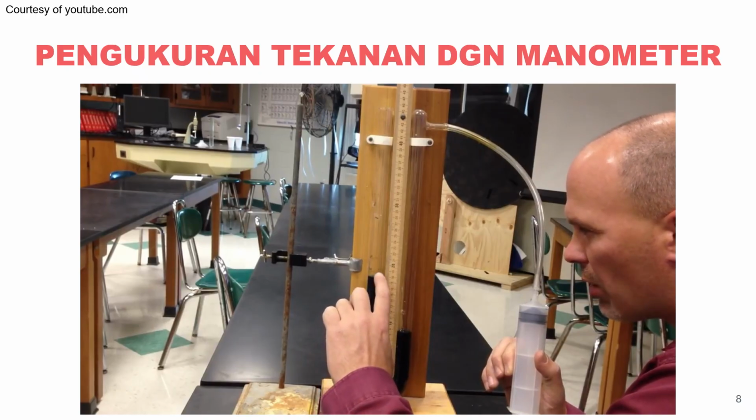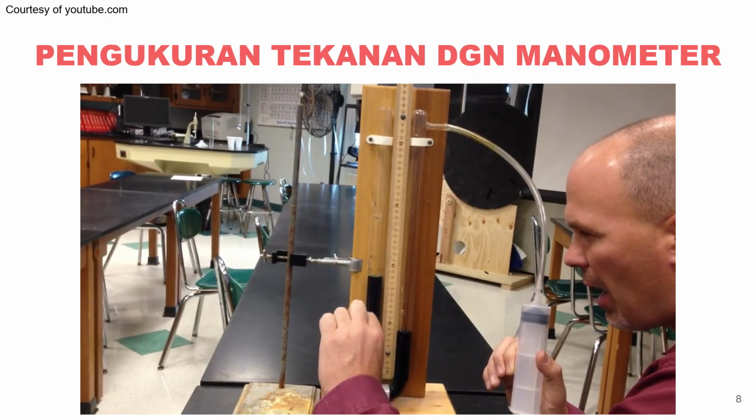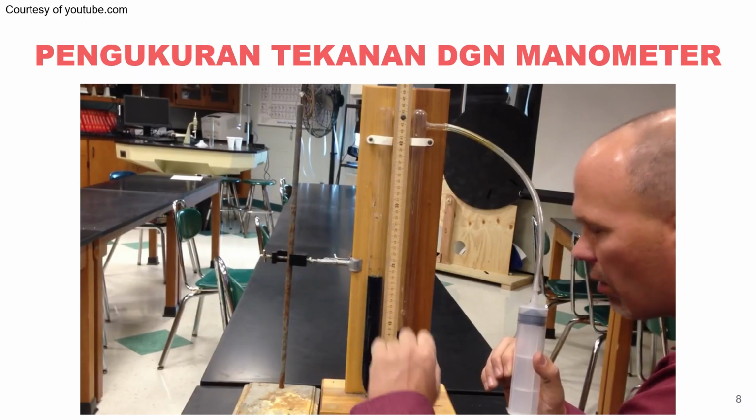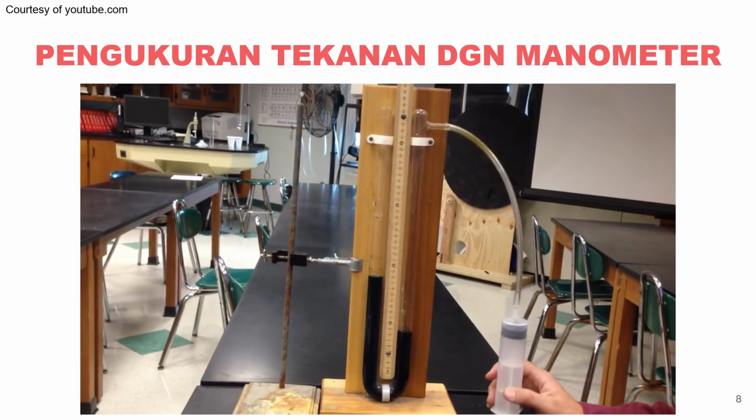So if this was water and I'm going to convert it to mercury, if we're going to use 190 millimeters, I divide it by 13.6, and that would be the height in mercury. So if we don't have mercury, we can certainly get there by doing those differences. So that's a little basics of manometers.